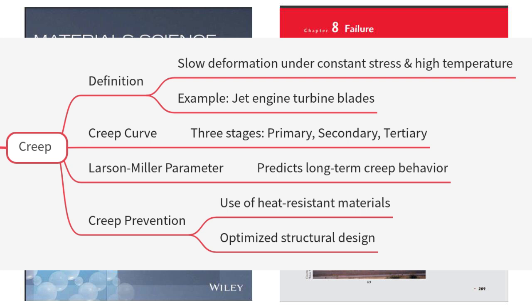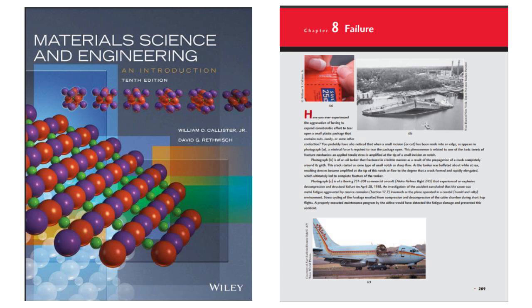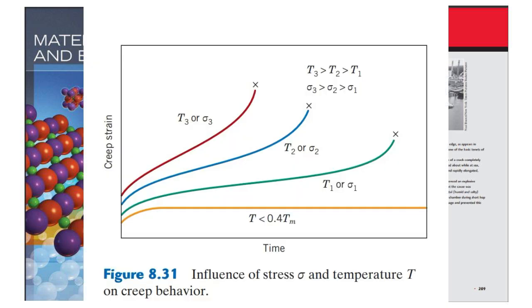So you can imagine a metal beam that's under a constant load, and over many, many years, it slowly starts to sag under its own weight. That's creep. So it's almost insidious in a way. It's insidious, it's slow, and it's very difficult to predict sometimes. The textbook mentions this S590 alloy,